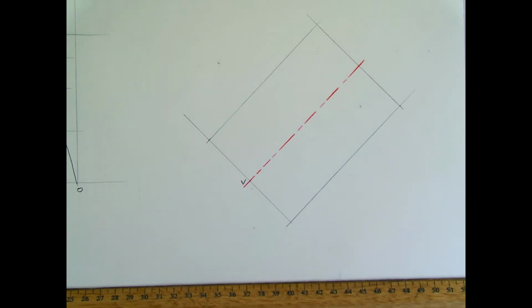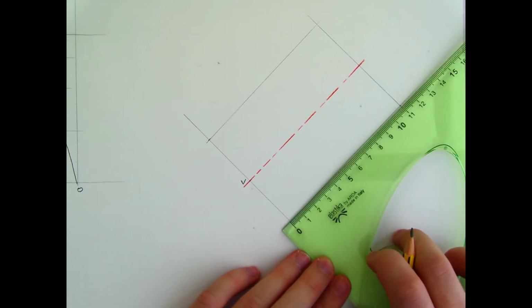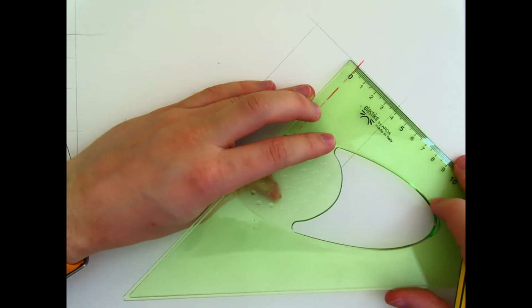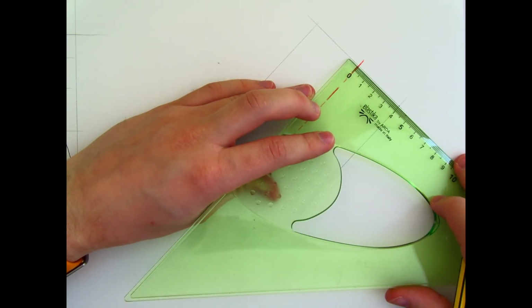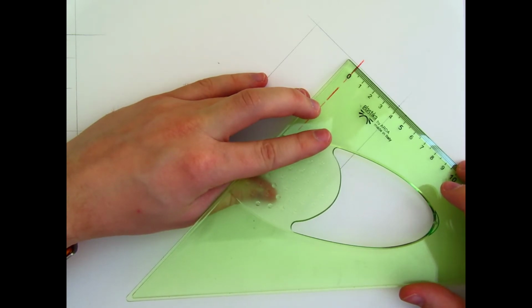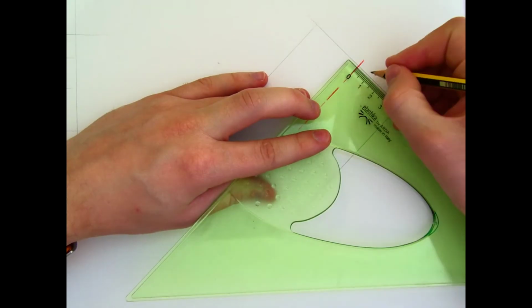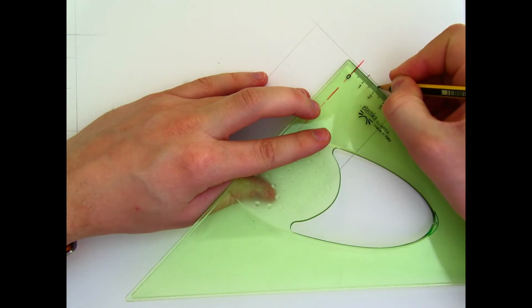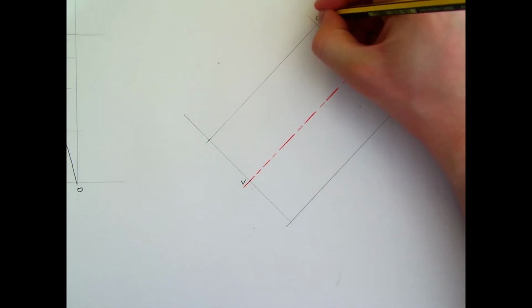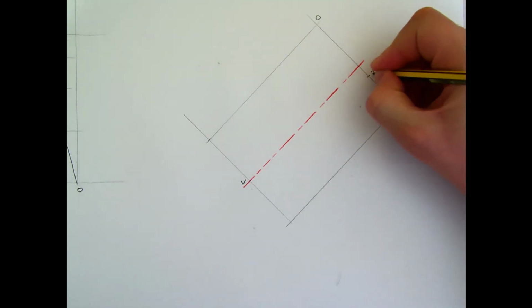Now we're just going to look at a parabola drawn at an angle, just to show that the principles are the exact same. So my side lengths here are slightly different. So the side length of this is 110, and the side length across the bottom is 40. Or the overall length is 80, but half it is 40. So I'm going to divide this up into 4 equal parts. So labeling my zeros first, then 1, 2, 3, and 4.